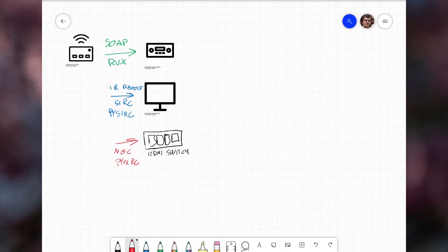So it speaks NEC, and I'm going to use this directly with a TRS connector. So that part is easy. I need an infrared LED, easy. You can buy them off AliExpress, or in my case DigiKey, because I wasn't sure which nanometer I wanted, and AliExpress was a bit iffy on that. You have a TRS connector, you have an opto-isolator just in case. Because yes, supposedly all the ground is grounded together, but let's not be fiddly about that.